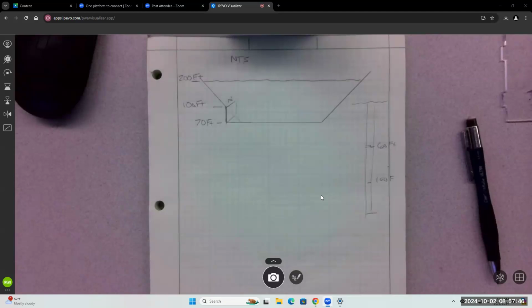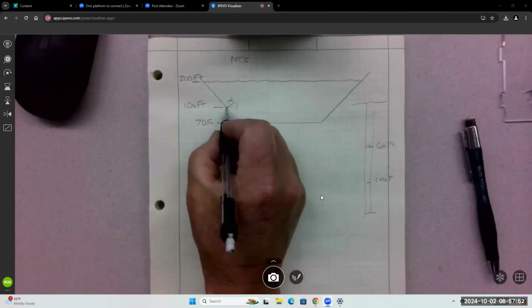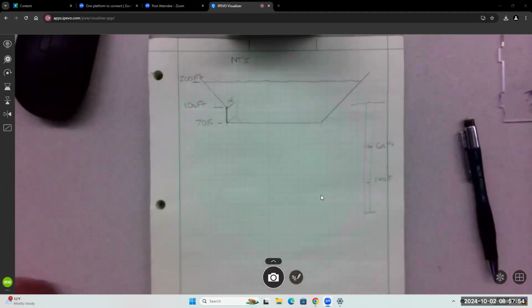But what you're talking about wasn't force, it was pressure. That's exactly right, though. We have to know the pressure at the bottom and the pressure at the top. We have to draw the pressure diagram and then concentrate the pressure diagram into hydrostatic force, the single force that's really pushing on this plate.